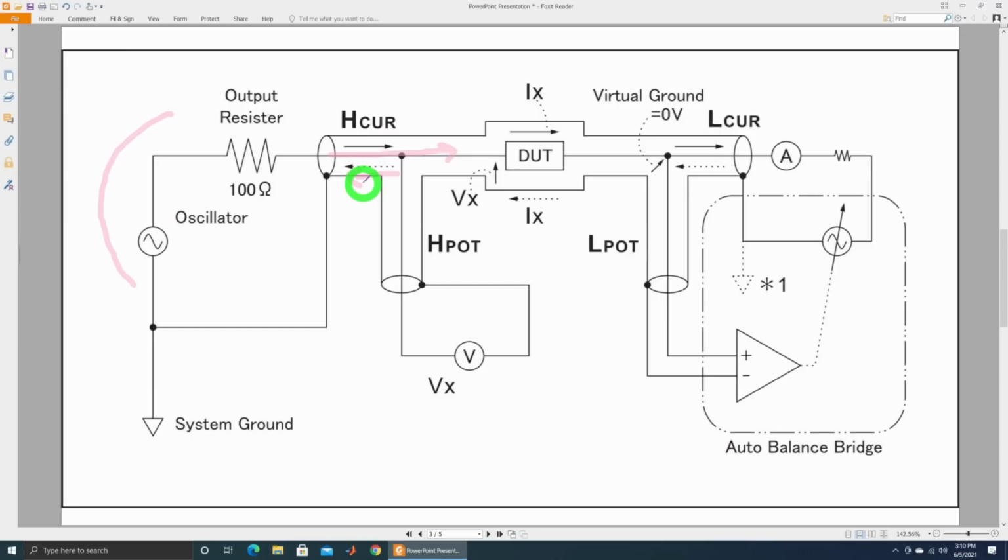So this is very, very useful. That means that you don't have to worry about how the cables are moving around or interacting with each other, because they're not producing any external magnetic field. But that doesn't end there, because even though they're not producing any magnetic field because they have current in the opposite direction, they may still have a voltage on them. And that voltage then interacts with the environment by creating an electric field. And then that would capture any parasitic capacitance that could be sitting there.